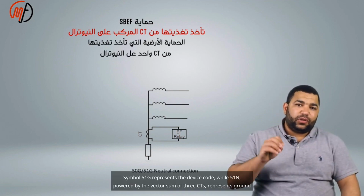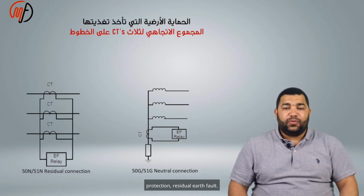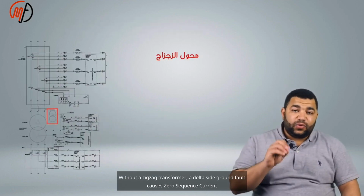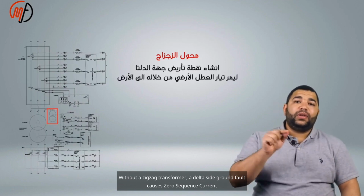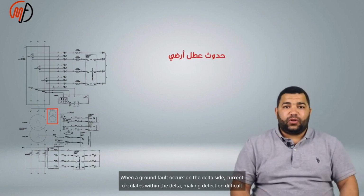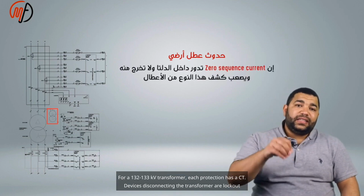Symbol 51G represents the device code, while 51N, powered by the vector sum of 3 CTs, represents ground protection, residual earth fault. The zigzag transformer creates a grounding point on the delta side. Without a zigzag transformer, a delta side ground fault causes zero sequence current. When a ground fault occurs on the delta side, current circulates within the delta, making detection difficult. Grounding the star side is easier. For a 132/33 kV transformer, each protection has a CT.